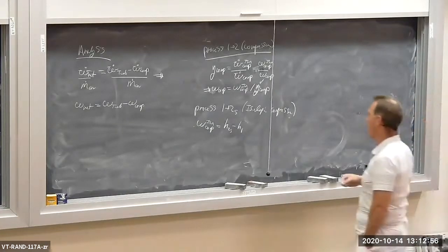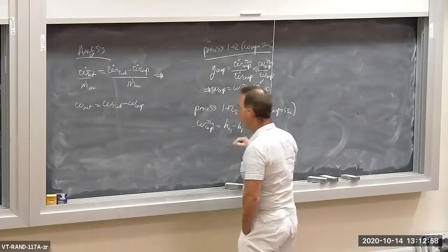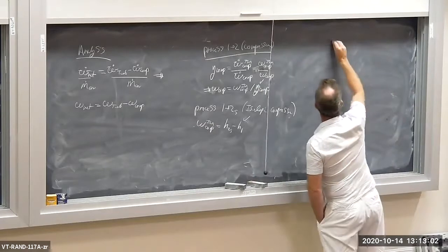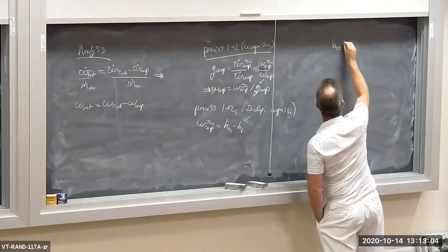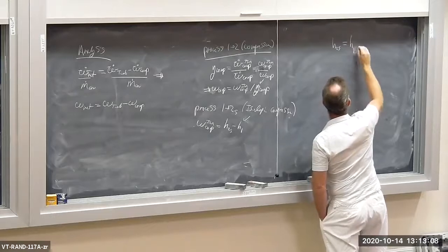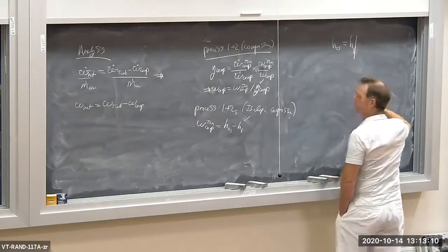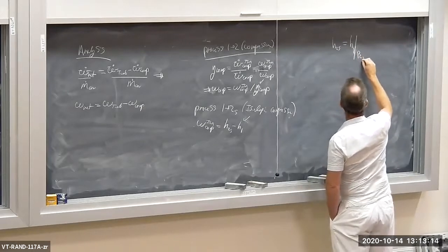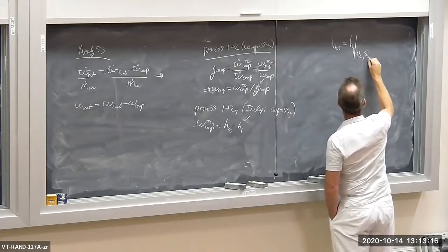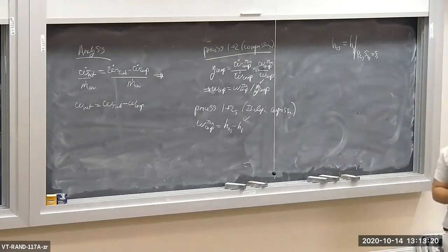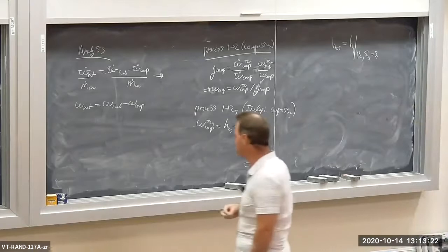Okay, so I know H1. I don't know H2 sub S. So H2 sub S is equal to H evaluated at a pressure P2 and S2 sub S equals S1. So it's an isentropic compression process where pressure is equal to P2.